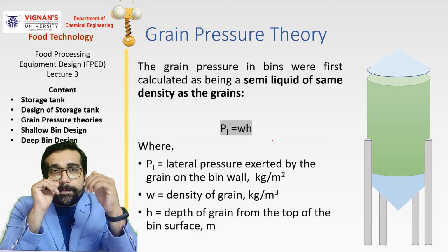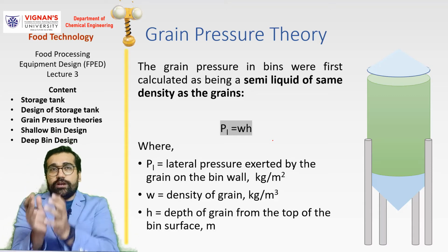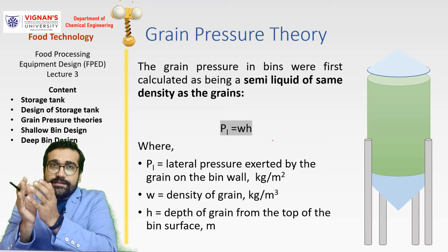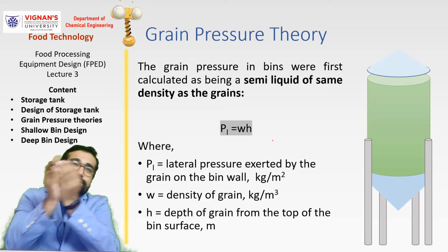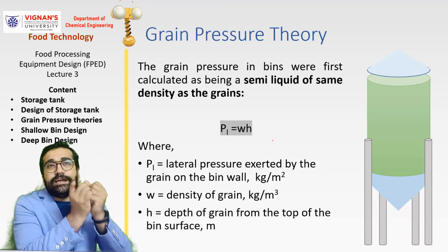We consider the grain as a liquid, not as a solid, shift the density of the grain to this liquid, and then design for liquid.